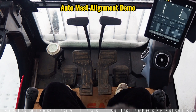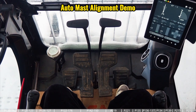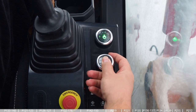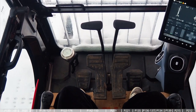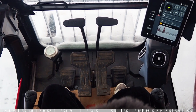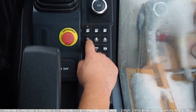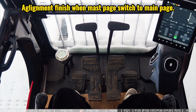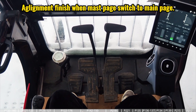We activate the mast manual movement and use a joystick to incline the mast a little bit, and also forward. So as you can see now, the mast is not vertical. So what we need to do is close the manual mast mode and then click the auto mast alignment button once. And then, as you can see, the main page is switched to the mast page automatically, and the function has been started. And when everything is finished, the page will return to the main page.